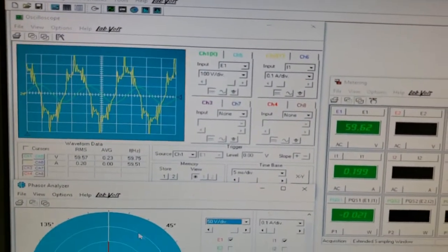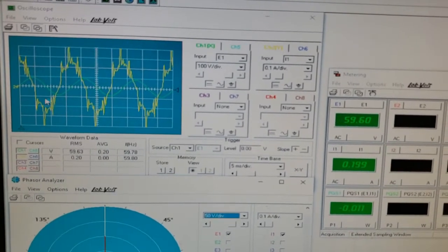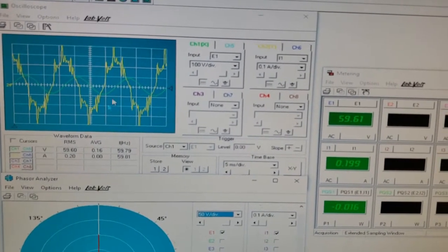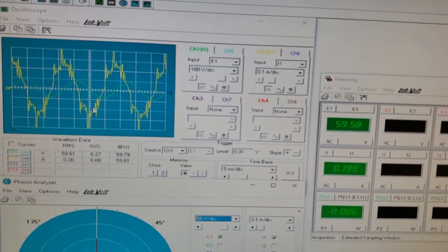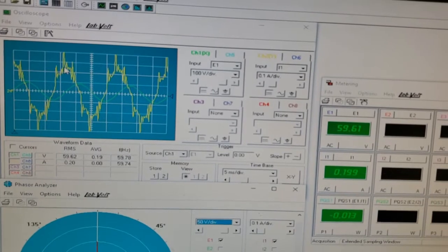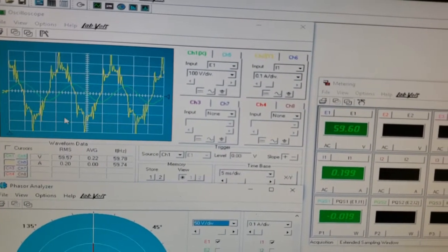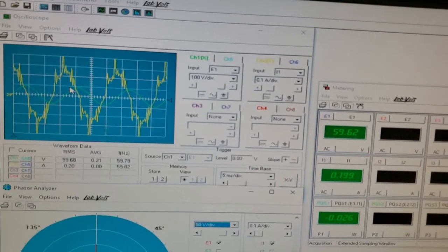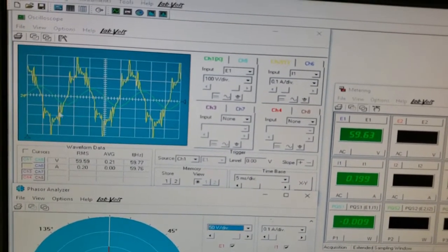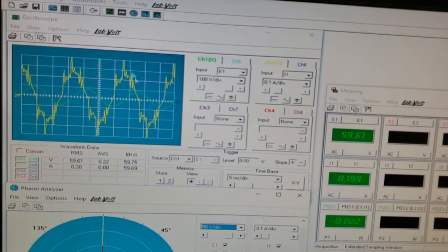What is that? What is this yellow waveform? First of all, imagine just the fundamental harmonic over here. This is the voltage waveform, and this is the current one. You can see now the current reaches its peak before the voltage. So we can see that 90-degree phase difference is indeed the case here between the voltage and the current, which we expect with a capacitive load. But there's also a ton of other harmonics involved here.